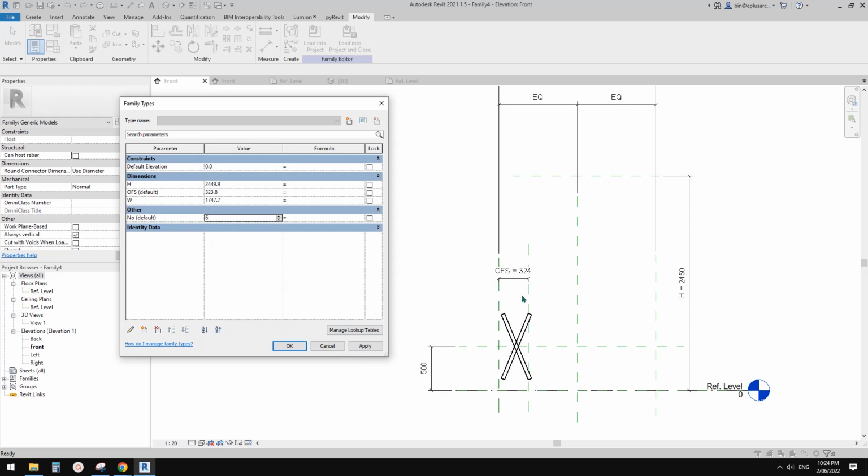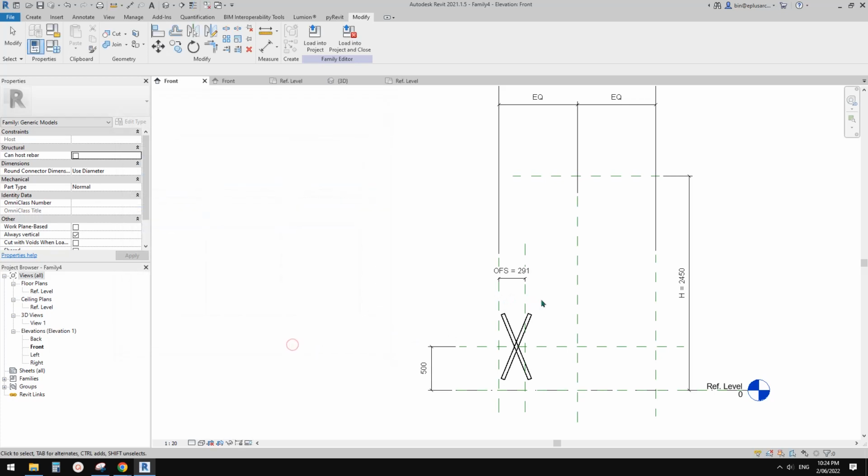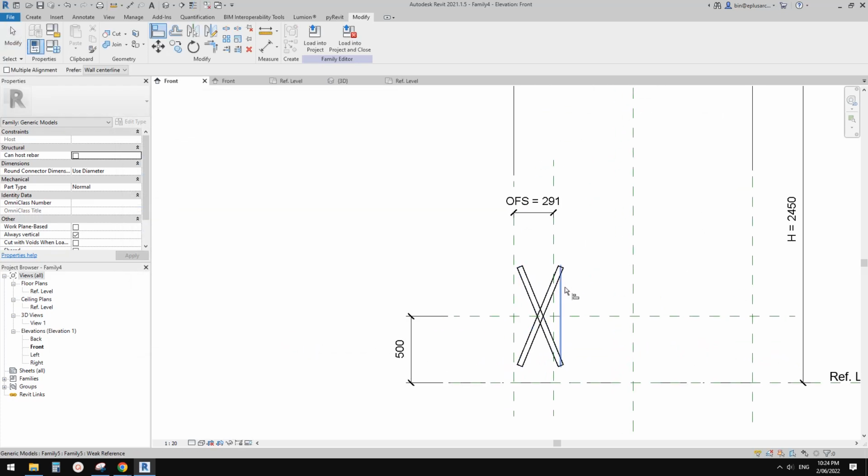And then we can use this number, and we can get the offset, which is the overall width, which is W. So go into here. So offset equals W divided by number. So capital W, capital N, lowercase o. So apply. So now that's the offset. So if we do an array, this is a distance.